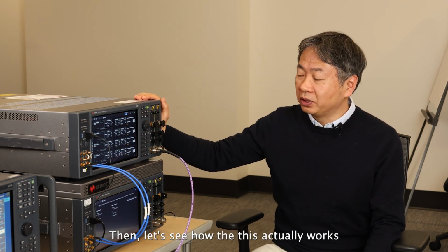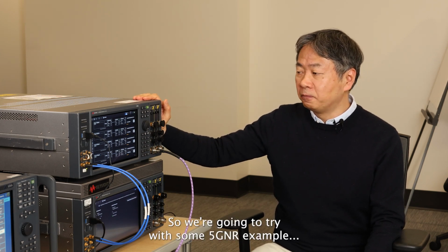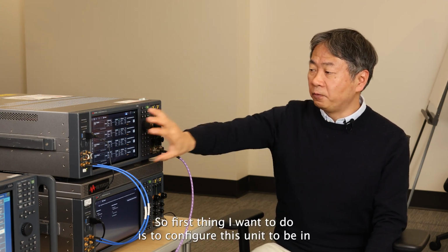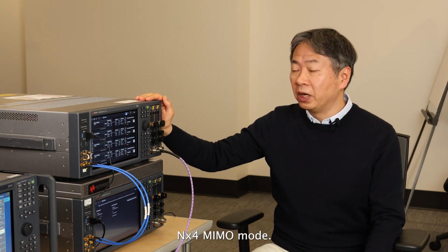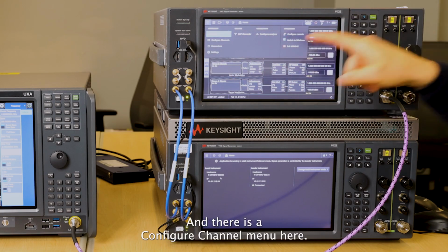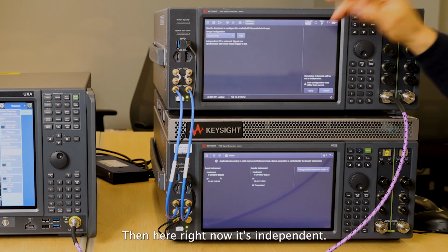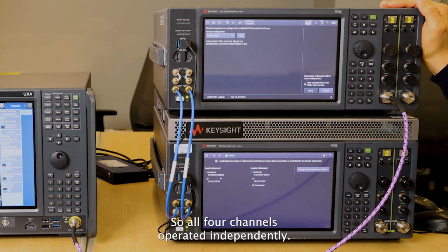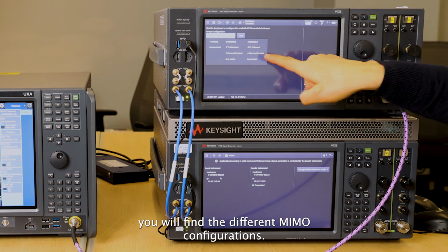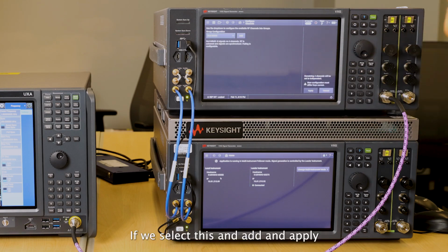Then let's see how this actually works with a specific application. We're going to try with a 5G NR example. First thing I want to do is configure this unit to be in N×4 MIMO mode. To do that, again, we select this hamburger menu button, and there is a configure channel menu here. Right now it's independent, so all 4 channels are operated independently. But if you press this drop-down menu, you will find different MIMO configurations. Here, we have an N×4 MIMO.